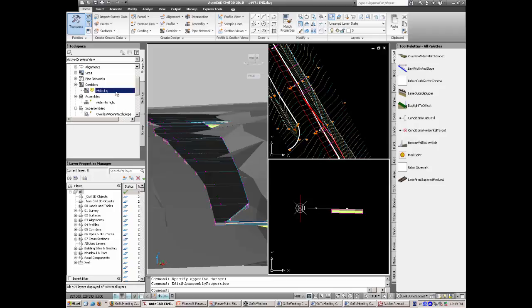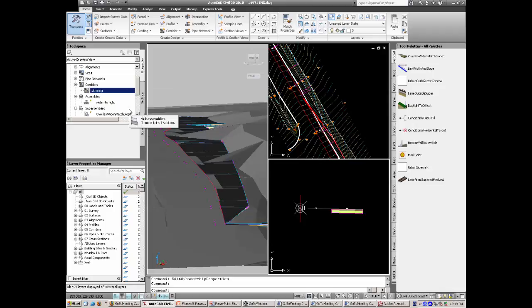Having done that, what we should now see on the top left here on the widening is that an exclamation mark has appeared. So I'm going to right click that, just give your screens a second to catch up, and I'm going to select rebuild. So when I press rebuild, you should watch the shade view on the left, and you will see that the road jumps down. So it's now blending exactly into the existing topography and pushing the grade out further. So that's how easy it is to model the actual widening.